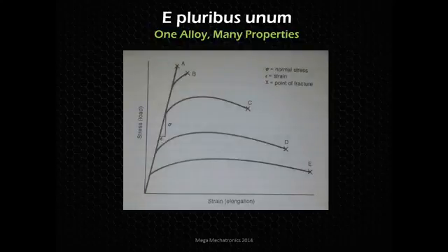So imagine this is one type of metal, one type of alloy with certain elements. We're not changing anything. The only thing we're changing is the treatment. So as quenched, straight out of after you heat it up to crystallization, you quench it in that water, and it's super brittle. It is strong, but it's so brittle. And you don't want to leave it, especially in a manufacturing environment when you're moving parts around. You don't want any cracks to form, people banging stuff around on the high-low truck.